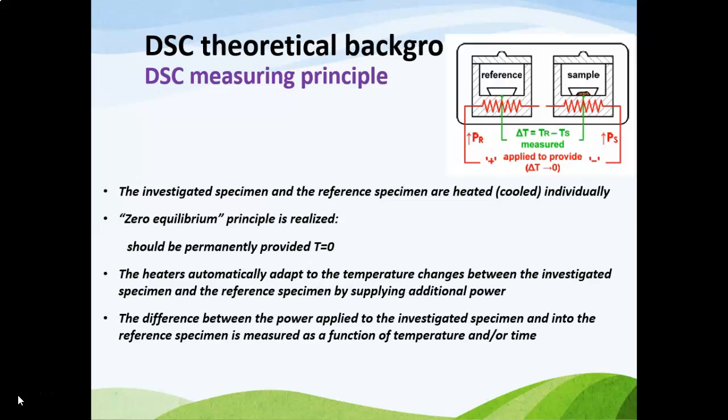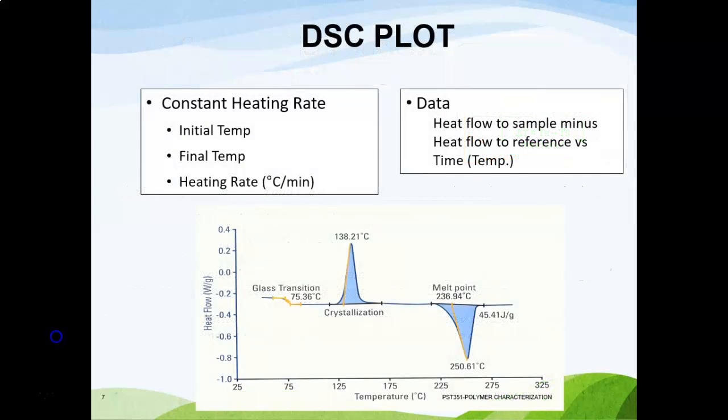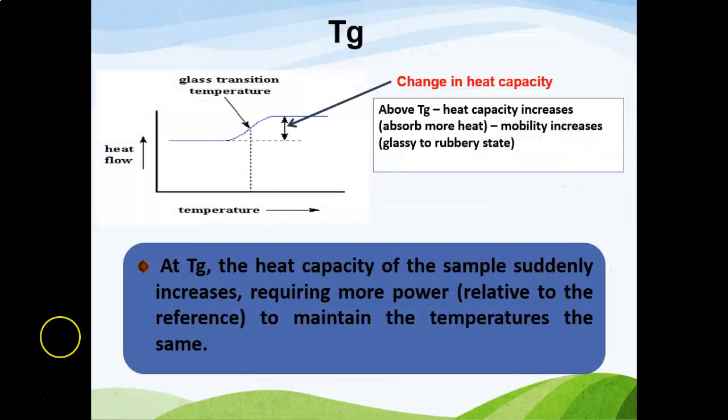and or time. Basically, DSC is a technique we use to study what happens to polymers when they are heated and also when they are cooled. We use it to study what we call the thermal transition of a polymer, which is the changes that take place in a polymer when you heat it. The melting of a crystalline polymer is one example. Tg is also a thermal transition, and it needs to be heated by using DSC.